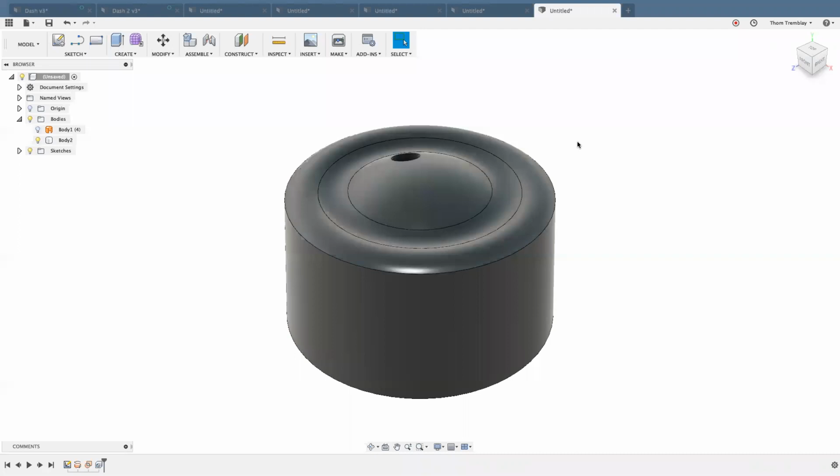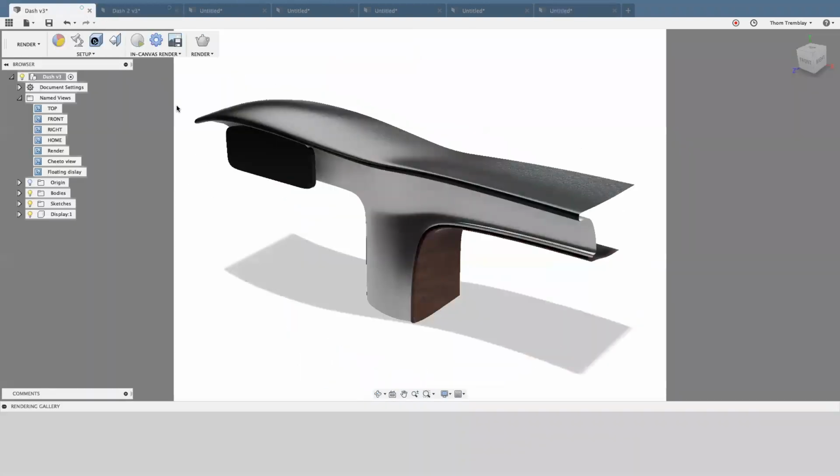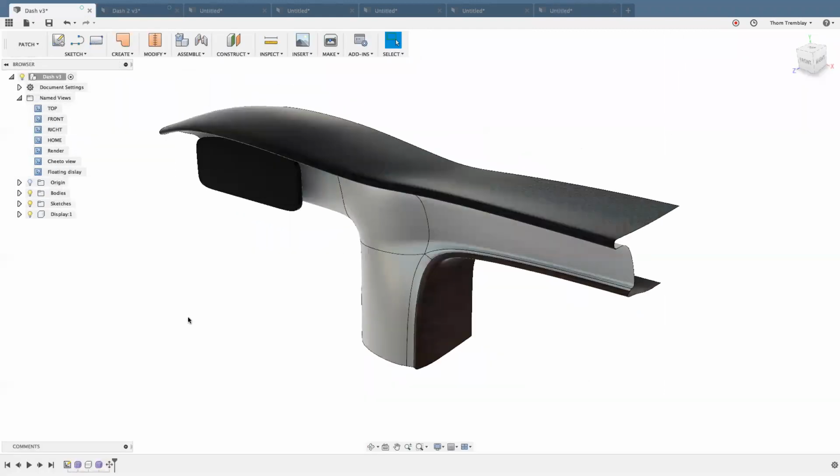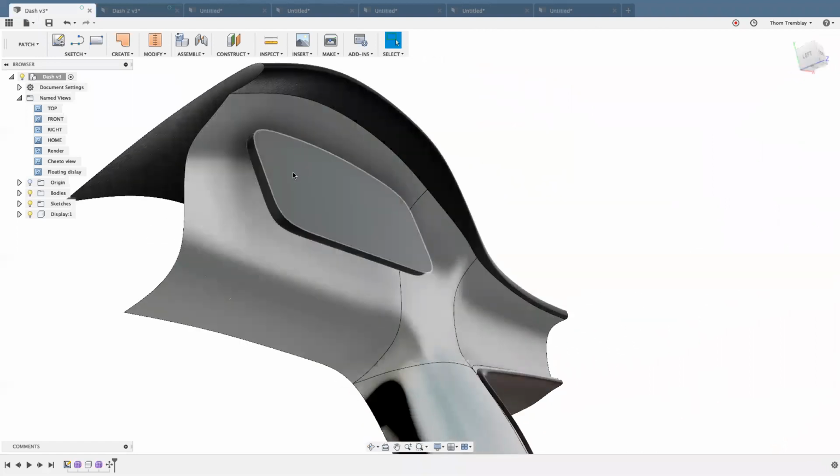Do you know of any ways that simulation can help our design in this scenario, just with you knowing what we're doing? It would really be more around the hardware or mounting. So for example, even without generative design, which is very cool stuff, I think I mentioned previously that there is shape optimization. Let's say on this oddball dash here, I created this dash to be floating out in space so that the display was floating. Let's say you were designing the bracketry or the hardware to hold that in place. What you can do is rough in a shape for that, apply the loads, and have shape optimization, which is an option in the version of Fusion 360 you have access to, tell you what material doesn't need to be included in your original design.